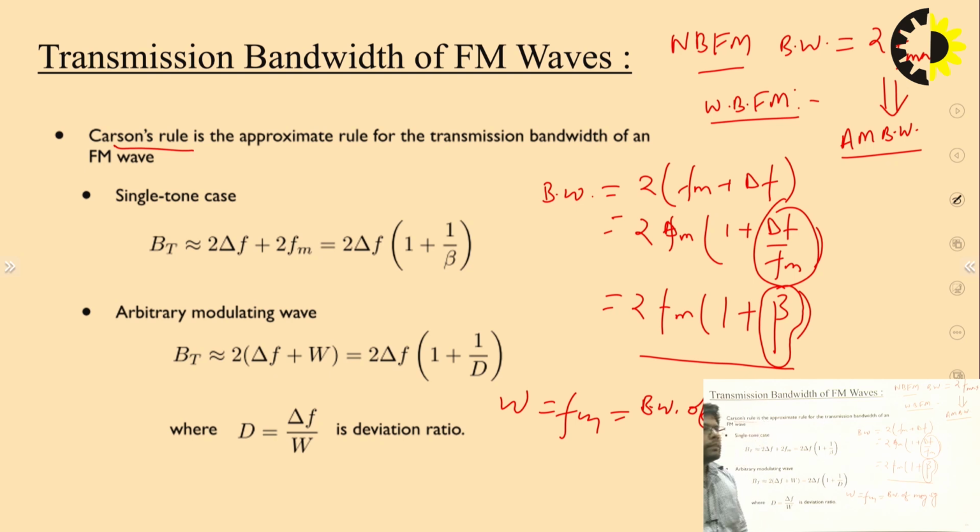In this lecture we have covered the topics of what analog modulation is, amplitude modulation, frequency modulation, phase modulation, and then narrowband frequency modulation, NBFM, and wideband FM, and also the Carson rule to calculate the bandwidth of the frequency modulated signal.